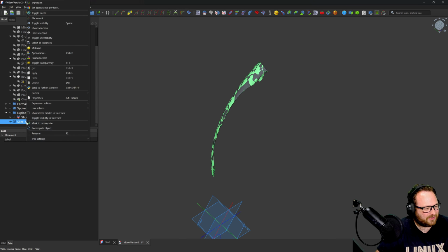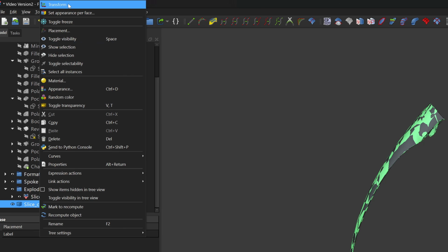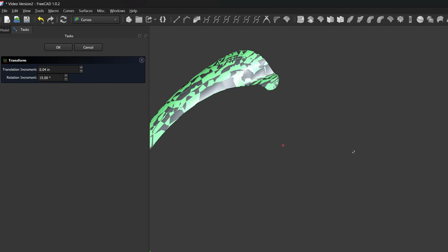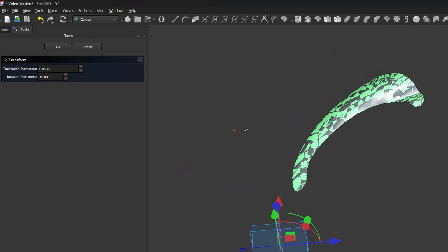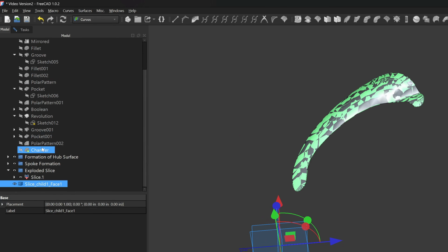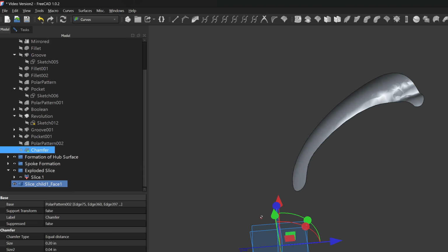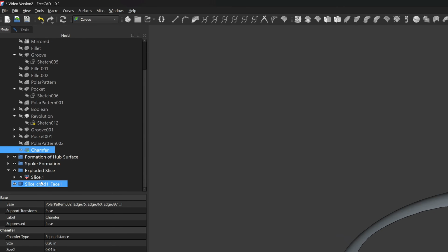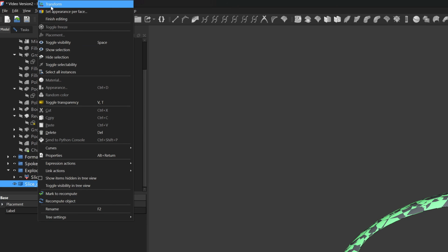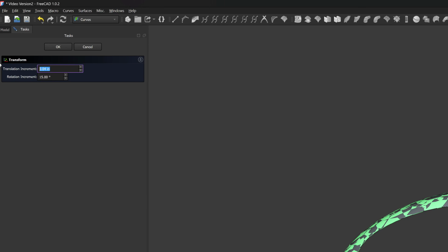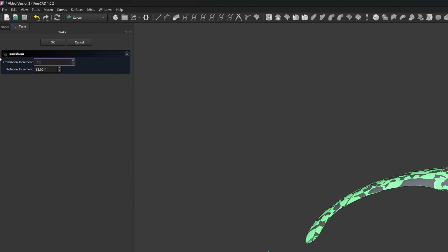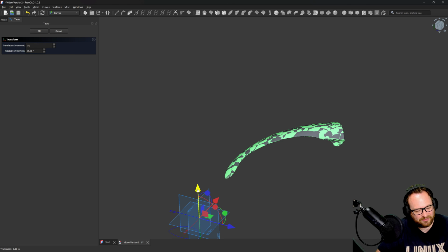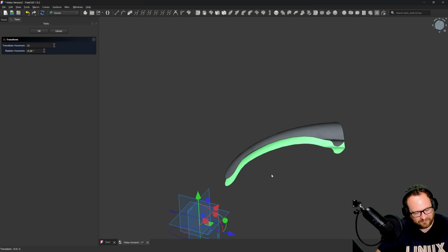And so I'm going to take this face, I'm going to right click, and I'm going to choose transform. We're just going to move this surface. I'm kind of losing my bearings here. I'm just going to show my wheel real quick. Okay, that's how we're looking. So yeah, we do want to move it down our y-axis, right? So we're going to say our child face is going to be transformed, and I'm going to transform it 0.25. So 1/4 of an inch, maybe 0.27. You know what? I'm actually going to say 0.51, and we're going to move that down 1 notch, and that's 0.51.